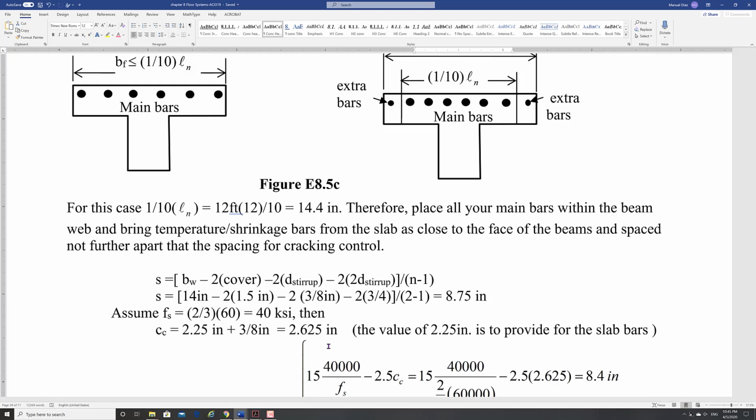Because that's going to happen. You're going to have bars in different directions. All the bars cannot be a 1.5 cover, right? So one's going to go below, the other one is going to go above, right? So you need to think about those.